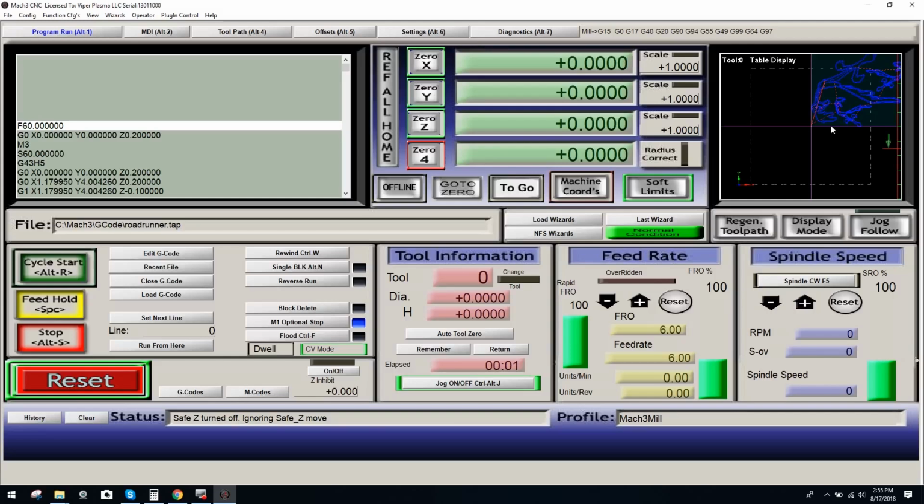Once again, there are variables. There are things that can happen. Weird things can happen. Anything can happen. But in all my years of using Mach, the main thing that happens when you're dealing with these settings is manual operations for machining. If you have hand wheels on your system, that can definitely throw the system off if Mach is off. If it's on, it's still going to throw it off because then you're fighting the motors. So you wouldn't do that anyways. I've had clients actually do that as well. So some things you'll find out the hard way.